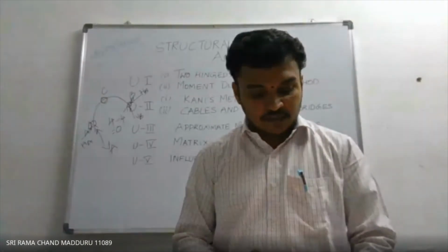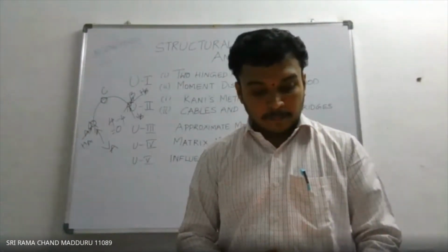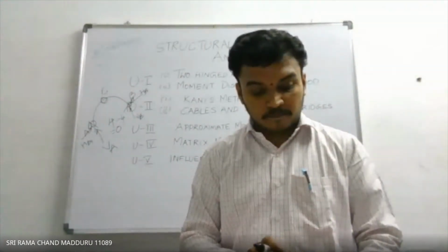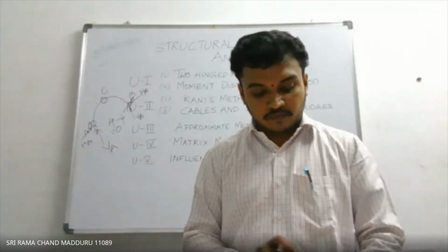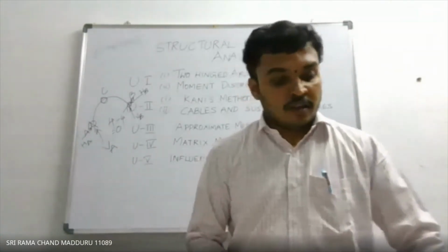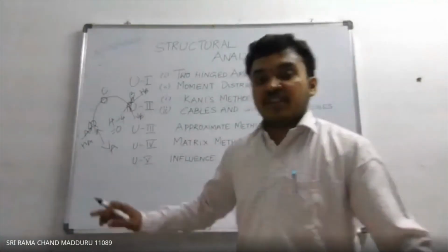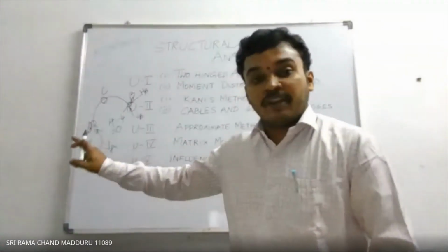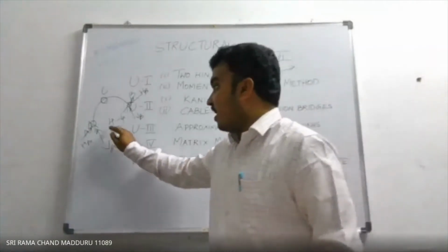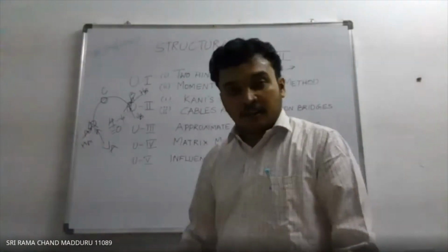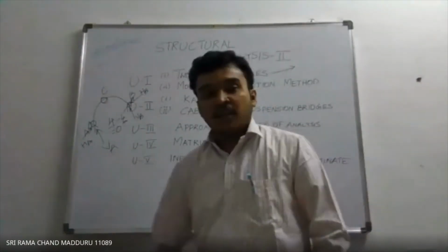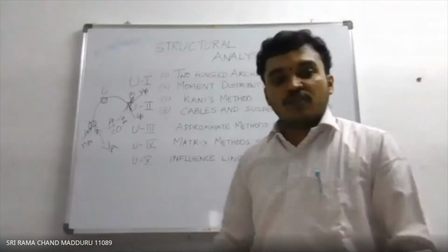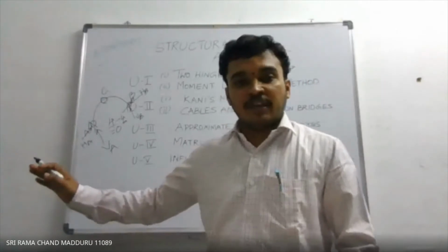So you can see that means the structure is a statically determinate structure. That means the number of unknown reactions minus the number of equations of equilibrium that are available, if it is equal to 0, we call it a statically determinate structure.